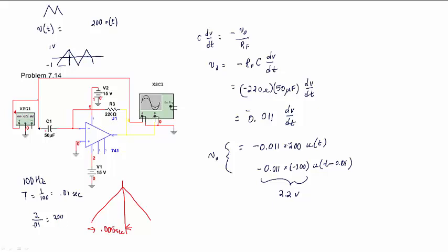So that would make this be 400 and not 200, and then I indeed get my amplitude as being 4.4 volts, which, yay, matches what I'm seeing on the oscilloscope, and my differentiator is behaving as a differentiator.